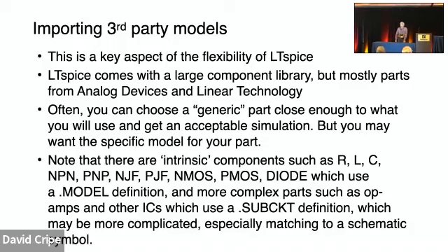Okay, here's a good spot to put in something about importing third-party models. There's a huge database, but they're mostly LT type devices and AD devices. There's some Maxim devices. A lot of cases, in my case at least, I'm doing like a proof of concept or something. So I might say this LT1015 op amp is just as good for my purpose as the TI op amp I'm really using. But sometimes you want the real thing. So you need to import a model from the third party.